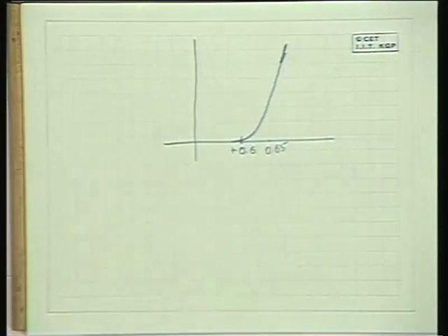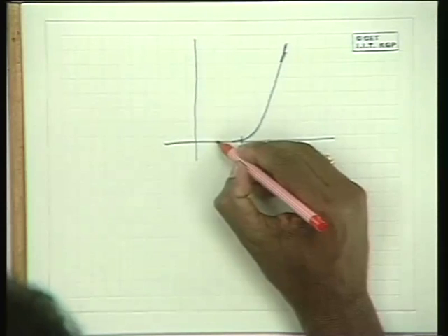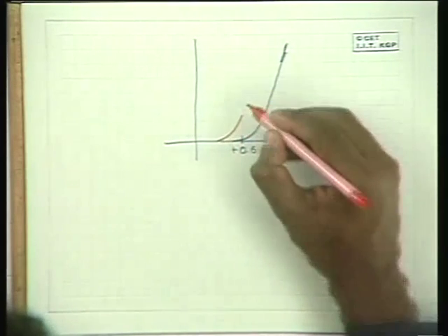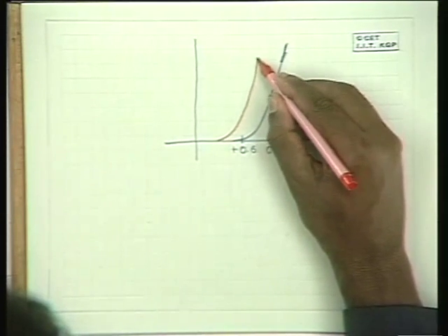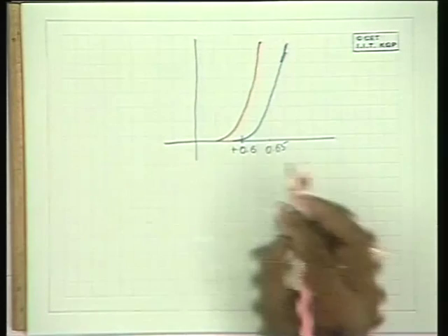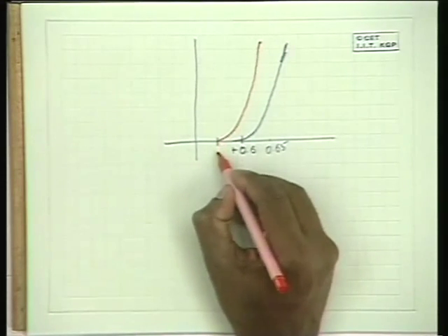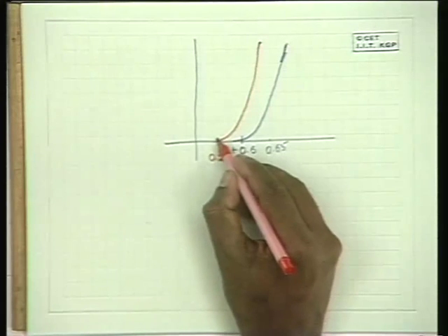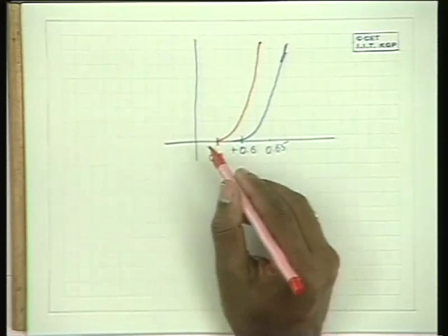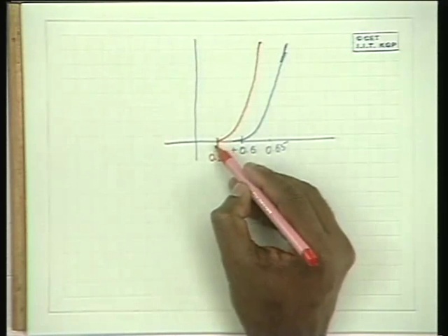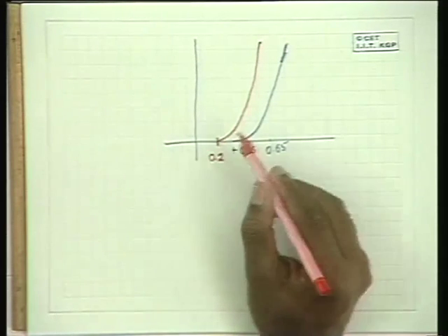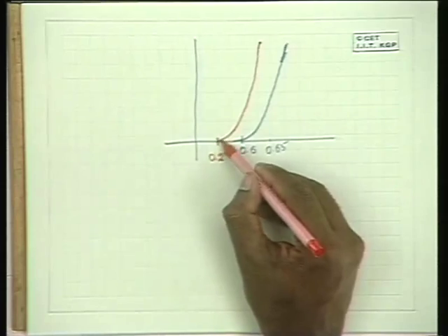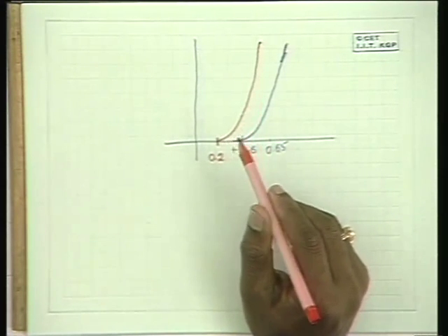On the other hand, the germanium diodes exhibit a characteristic of this type, with a voltage known as the cut-in voltage of about 0.1 to 0.2 volts, below which the current is negligibly small, and above this voltage it is appreciable.